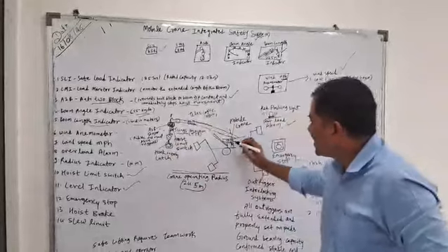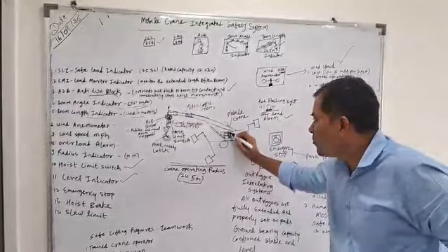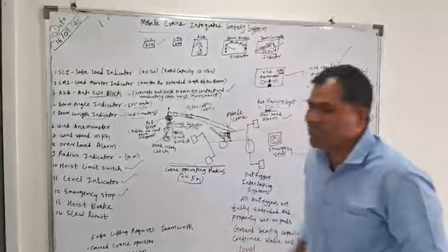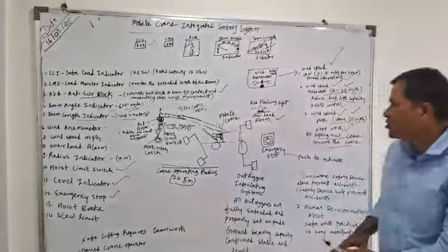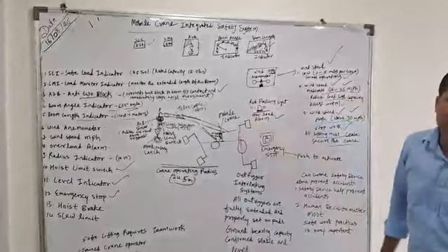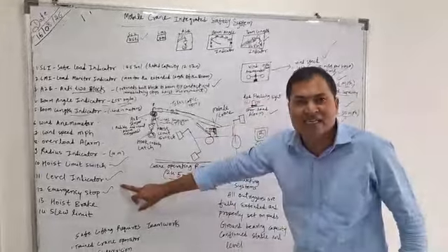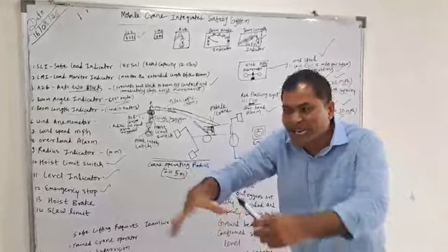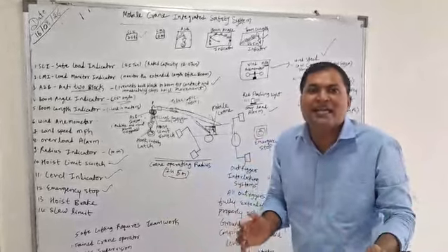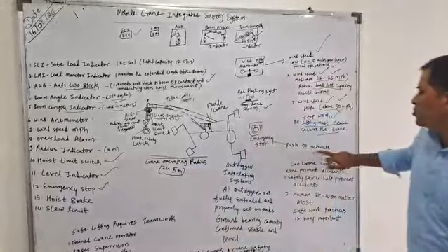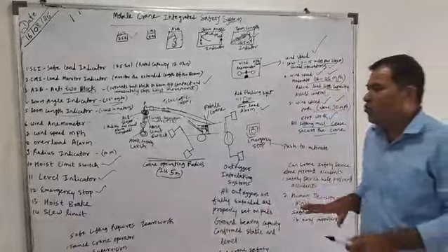Level indicator, here again the level indicator, what amount of level you want to manage. If something goes wrong, we have the emergency stop button. Immediately press that button if something goes wrong. Unsafe act, unsafe condition, something like obstacles in your work area, immediately press that button. Push to activate. Okay, the whole operation stops.